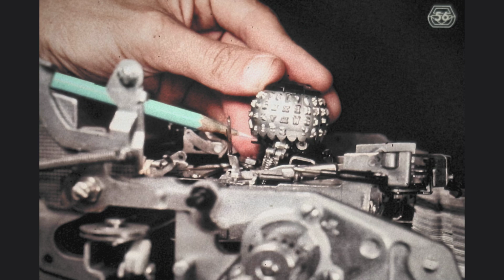When the machine is at rest and you manually tilt the element into its horizontal position, as shown here, from the side you can observe the clearance, or the distance, which exists between the skirt of the element and the rotate detent. That distance should be equal to 0.89 millimeters, roughly the equivalent of the thickness of the flat portion of the IBM spring hook.